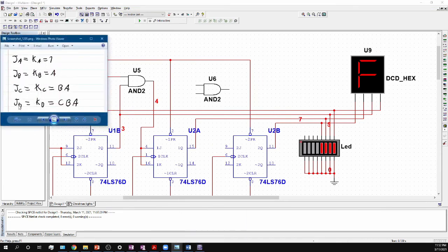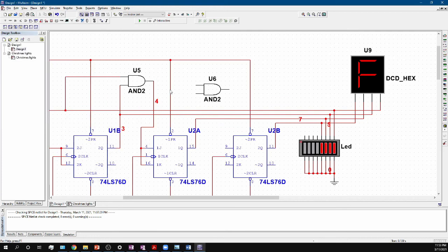Now it's telling me that I need to hook up the D flip-flop. I need to hook it up with, you can interpret this as a 3-input AND gate. Or what you can do is get the output from the previous one and treat it as a 2-input AND gate. So you can take the output of B and A, and put it into the second AND gate with C, and you're not going to have a need for a 3-input AND gate. So this will save some time and, more importantly, logic gates. So let's go ahead and do that.